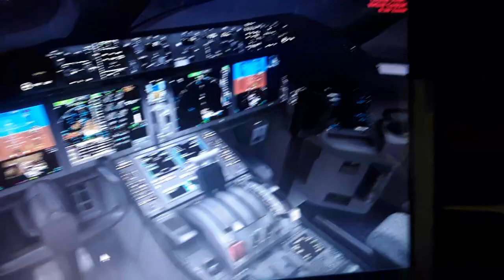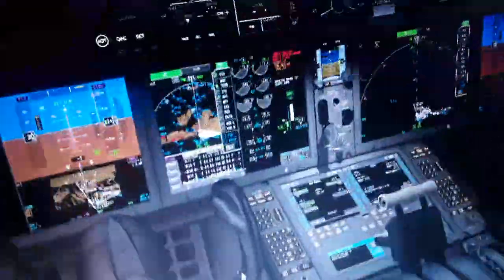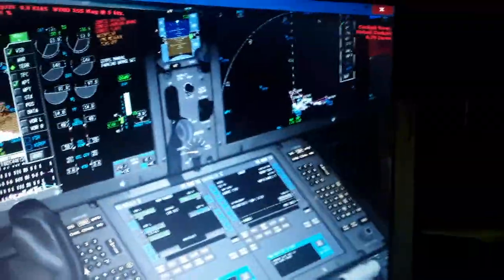So we're going to see a couple more things, more thrust, if we need idle thrust also. So this is how you control both the flight controls with this side stick and the thrust levers. Also you have the horizontal trim stabilizer, so you can control the horizontal trim as you fly. Advance the thrust levers, pitch up slightly on the runway for takeoff, use the rudder pedals for nose wheel steering also, and use the horizontal trim.